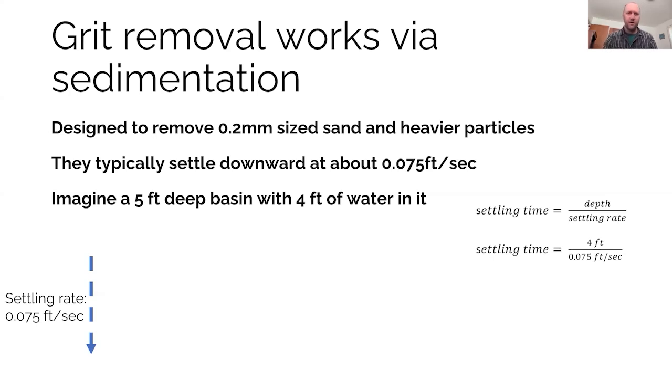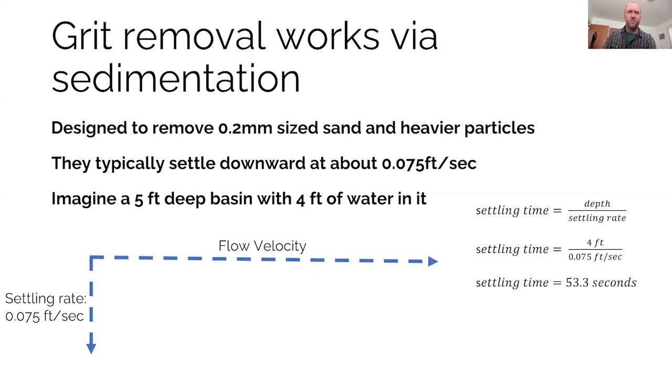So we have 4 feet of water. That's the column of water that the sediment needs to settle out of, and that's the settling rate. If we do that math, it's going to cross out our feet units, and we're going to end up with seconds. We're going to end up with 53.3 seconds. So that's the time it is going to take for the sediment to settle out in this scenario.